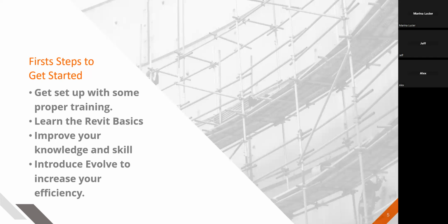Material takeoff schedules. So yeah, Revit can make material takeoff schedules. It can make quantity schedules. You can do part schedules, plumbing schedules, electrical schedules, panel schedules. Anything within Revit that is placed or has some kind of information, you're more than likely going to be able to schedule it. And if you can't, there are definitely ways to create custom parameters and shared parameters to do so.